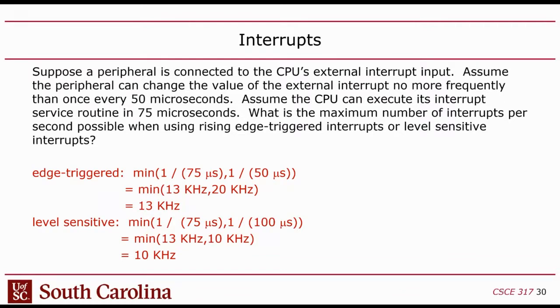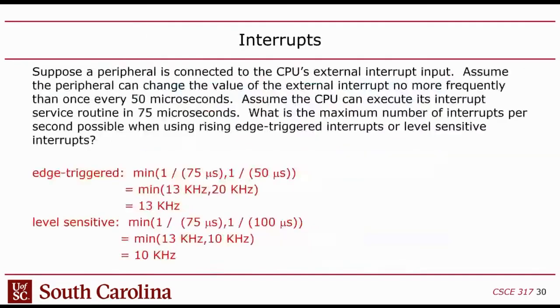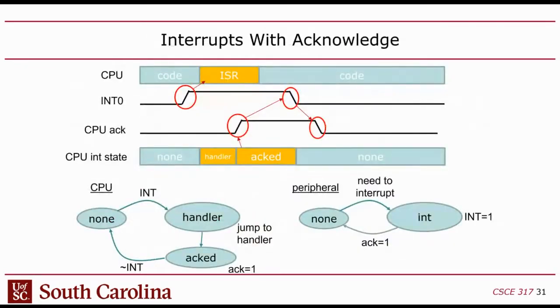Now, that's assuming that you don't just leave it high all the time, which you could argue, but I'm assuming that we're toggling the interrupt line. So in this case, the bottleneck would be the interrupt wire, which would be 10 kilohertz, changing it once every 100 microseconds. Although, like I said, technically you could just keep it high, like I show in this picture at the top.